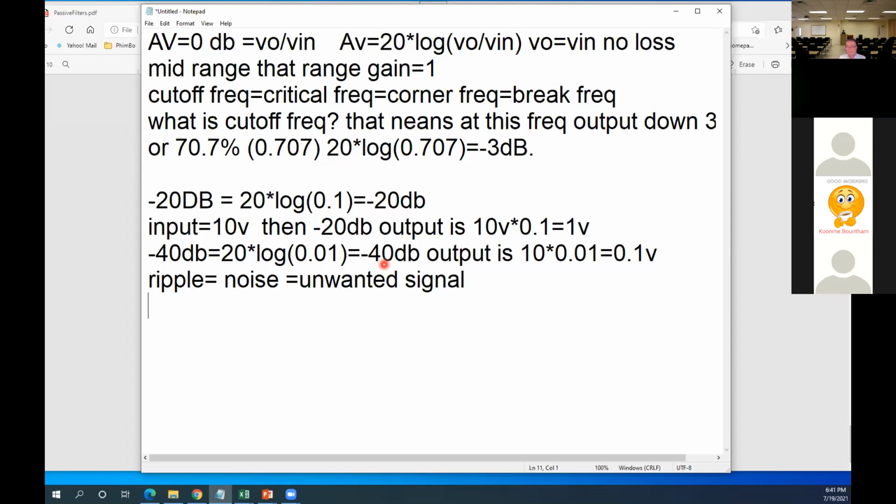When you design circuitry, like I did in the company for the government, they will ask you how many percent of ripple is accepted. Maybe 0.001%. So when we finish the unit, we must test to guarantee the ripple is less than that number.